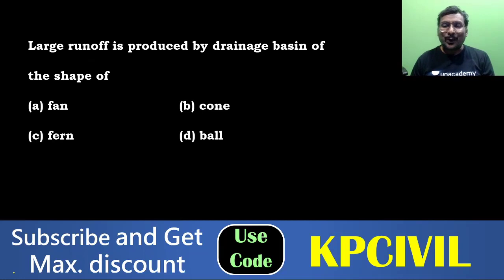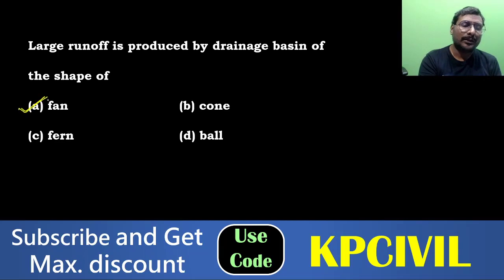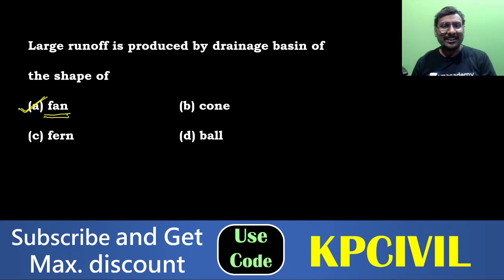Large runoff is produced by a drainage basin of what shape? Have we discussed it in the previous theoretical session related to hydrograph? We discussed it clearly. Two types of shapes, fan shape and fern shape. Which is providing large runoff? 100%, no doubt, the fan shaped catchment is providing huge runoff, large runoff.